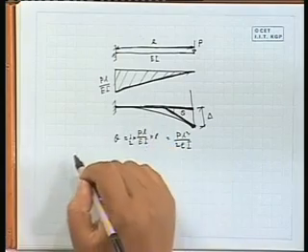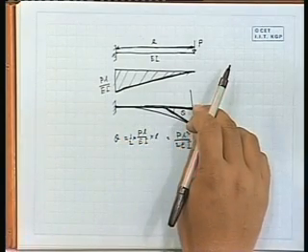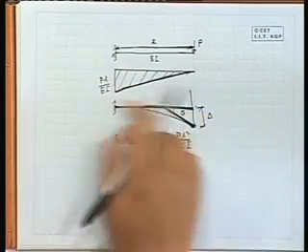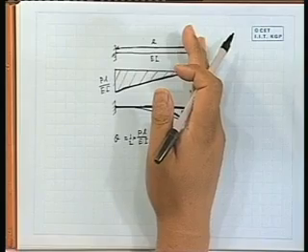Similarly, if we want to find out the deflection delta, try to remember the second part. Second part means, from here, this is the deflected line. From here, if we move perpendicular to the initial line, right, we will meet a tangent drawn at the other point. So, that is the deflection, meaning the area of the curve we have to take the first moment of area about this, because we are moving about this point.